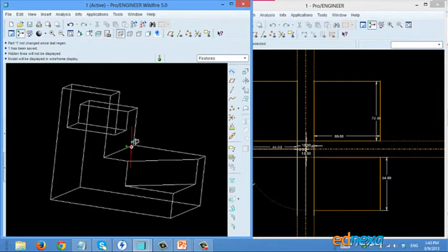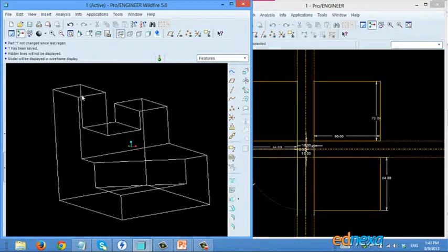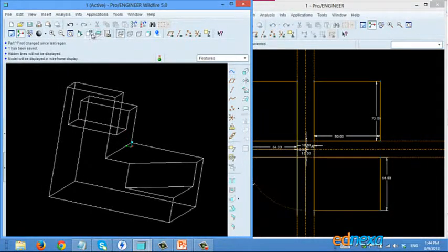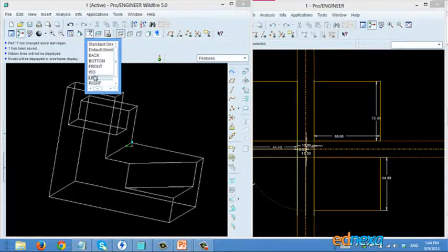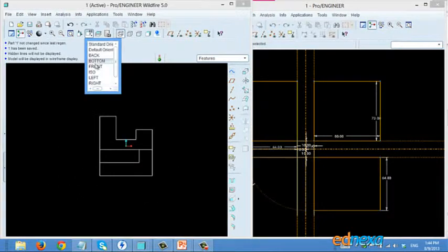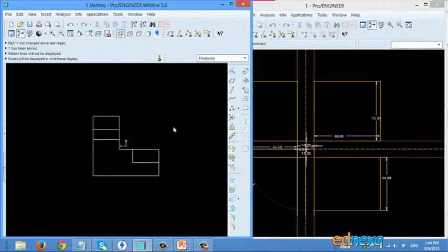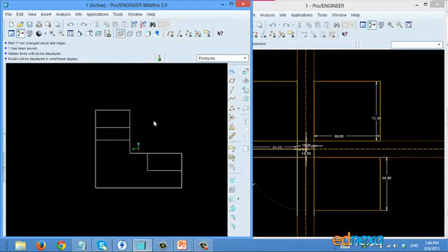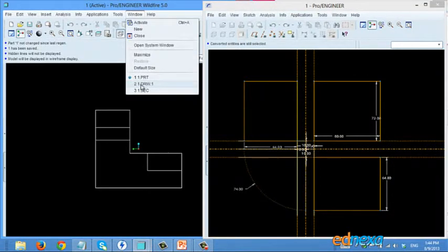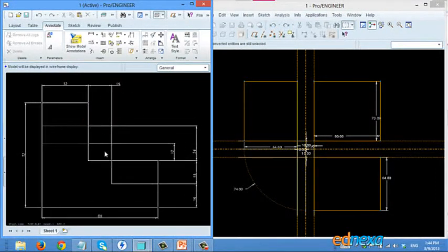Why are they hidden? Because this object in the front view is far larger than these two. So these two lines are hidden behind this object. That's why they must be marked hidden in the drawing, so that the person who is manufacturing can know the structure and can imagine the structure of the object. So we'll start drawing these views. For that we have some dimensions like this.